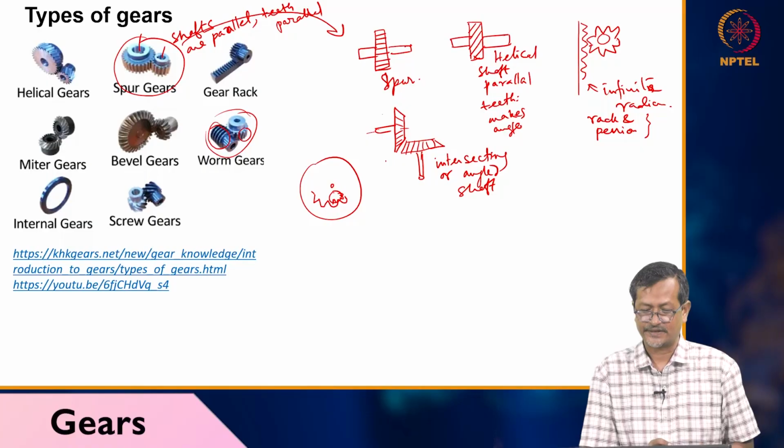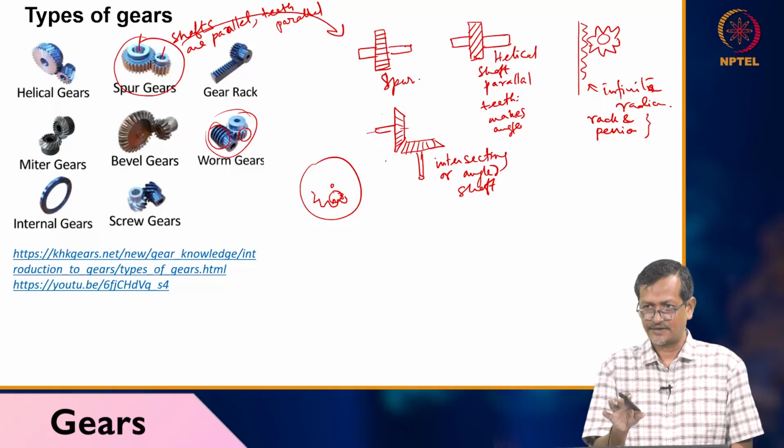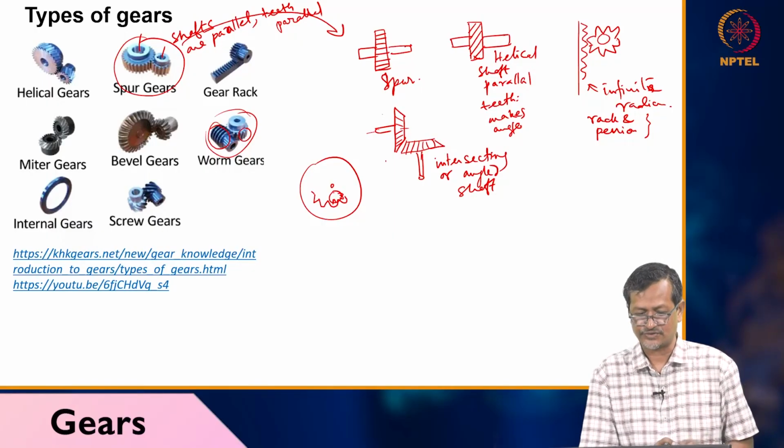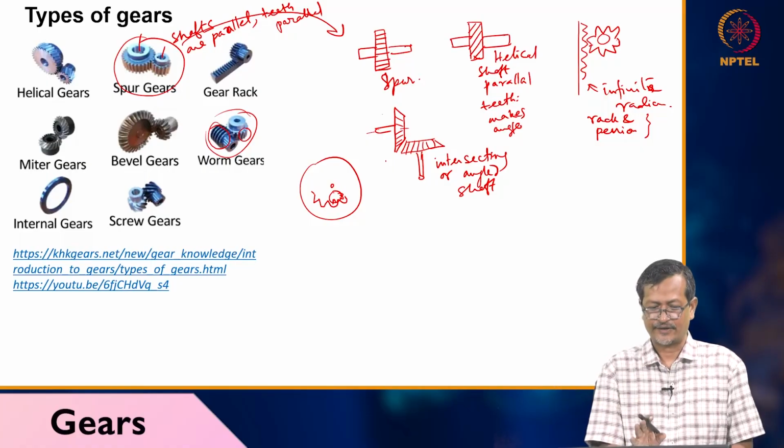The most common will be spur gear, bevel gear, rack and pinion. I am already using them for my wave energy converter. These are different types of gear, and they have different applications. For example, for my wave energy converter, I have to use only rack and pinion. I cannot use spur gear. Similarly, whenever you have two shafts and you are changing direction, you have to use bevel gear. Spur gear will not work.